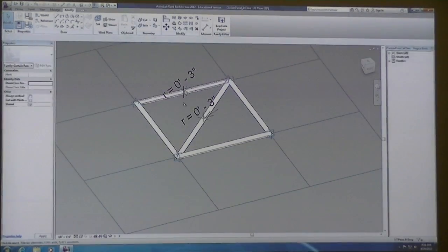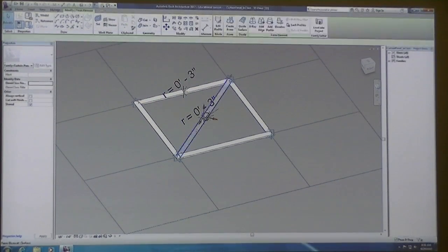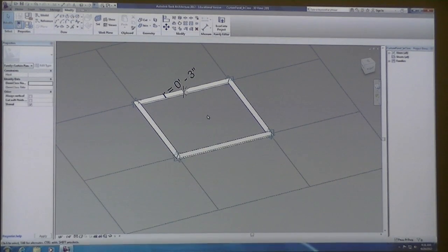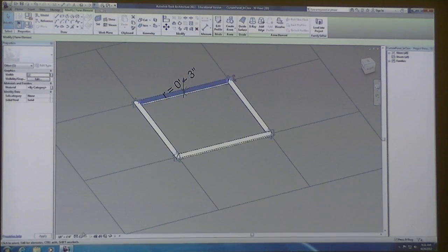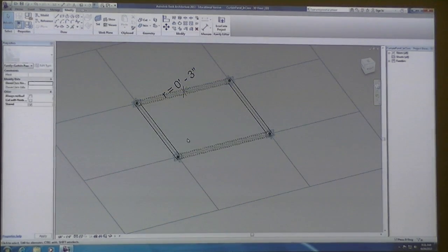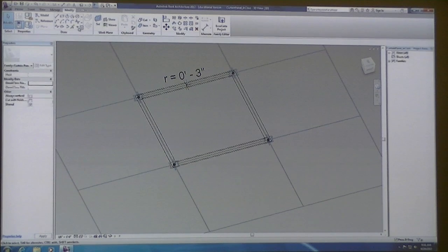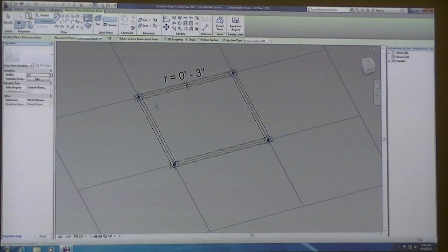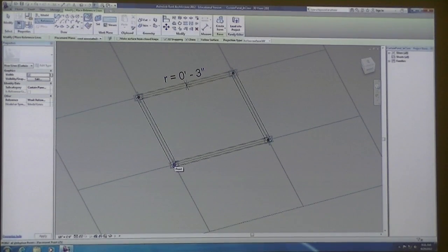And so I need to go back here, and unfortunately, when you run into that problem, you have to start over. So I'm going to draw this reference line. I've got my 3D snapping on. Did it not work because 3D snapping was off before? Yeah, for some reason my 3D snapping was off, and I didn't get the blue planes that showed up. So yeah, 3D snapping, we always want that to be on.